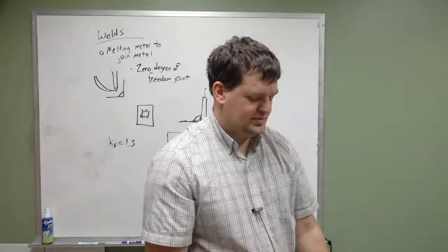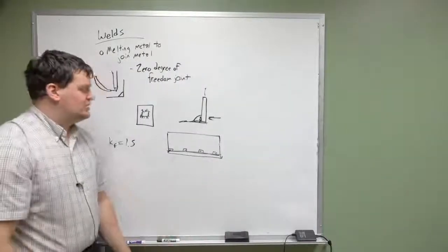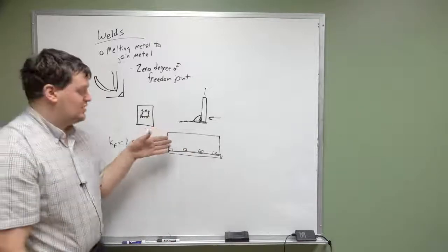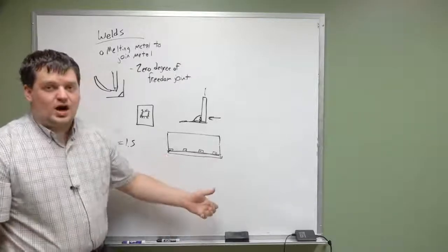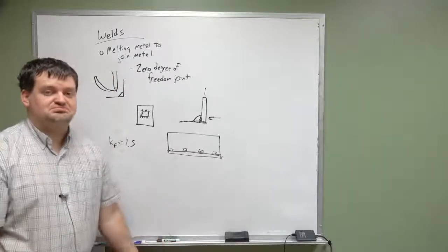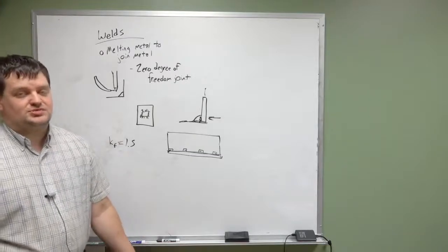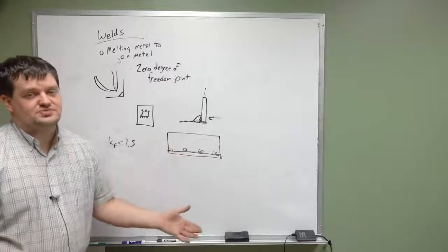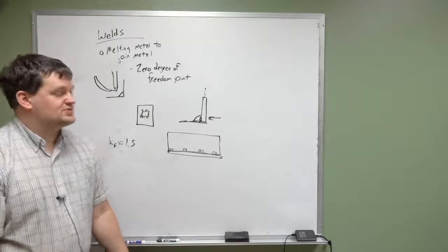Well, anyways, that's it. When it comes to welds, you really just have to figure out how much force is being transferred through this joint, figure out an acceptable material that you're going to be using, and then figure out how wide and deep those welds need to be in order to transfer that force. That's it. You did a lot with force transmission in calculating the power that goes through your mechanism. You do a lot with force transmission again to figure out how much force is being transmitted through the welds. And that's the gist of welds. It's very straightforward.